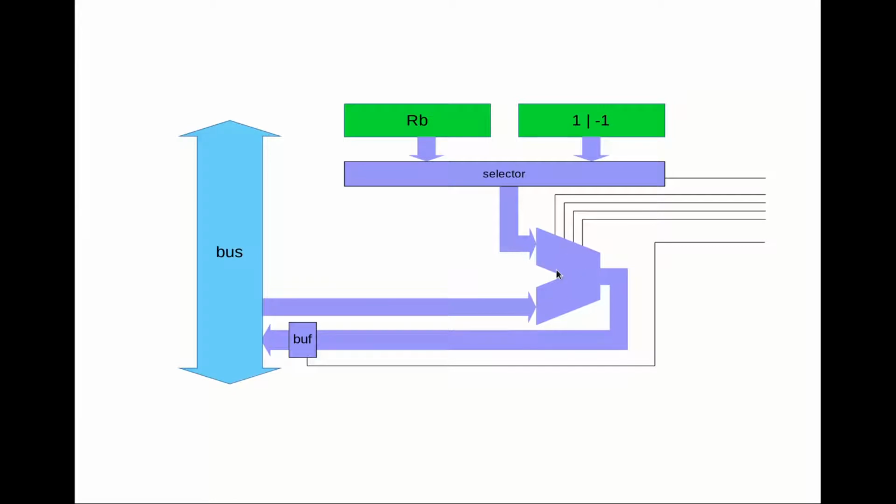Because there's no sort of latching in this ALU. The ALU consists of a simple circuit of logic gates. It doesn't latch anything. So we have input wires coming in here. It's pure combinational logic, and the result goes out onto those wires. And it's doing that permanently. It's hardwired, well, more or less hardwired that way.